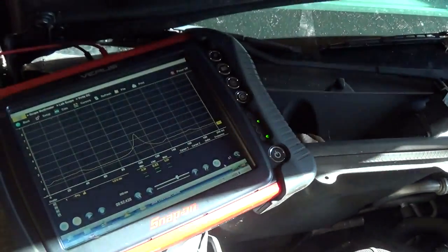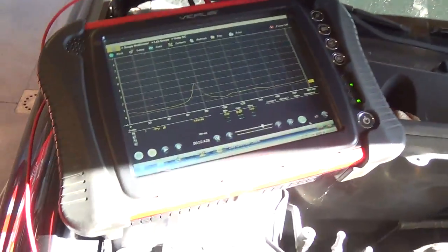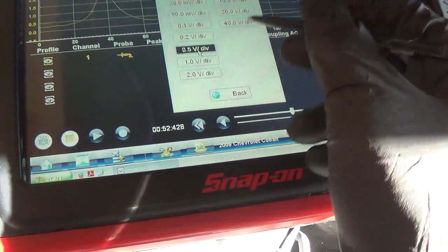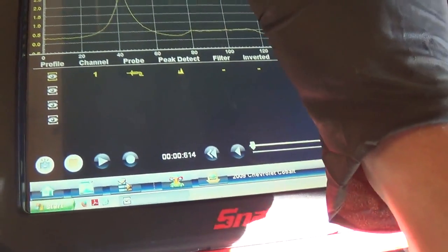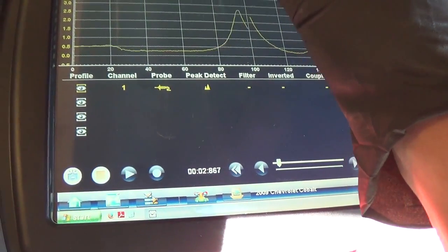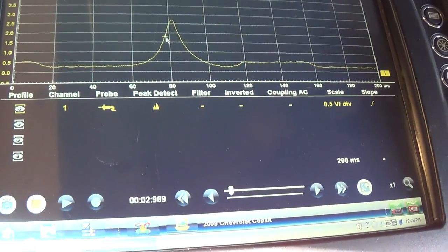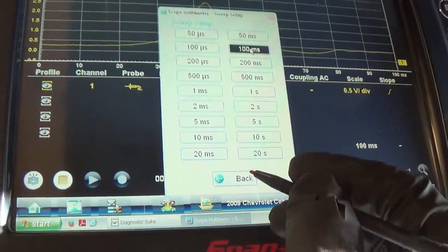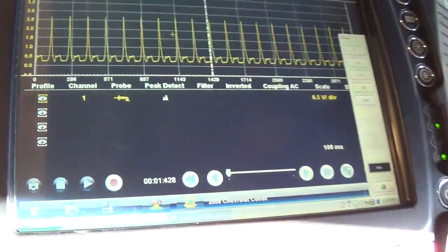Well, okay, we have a 2-cylinder misfire now, right? So let's drop this down. Since we're not looking at very high pressures, let's trigger on a rising edge. Right there. Okay, perfect. So 200 milliseconds, we can even go 100 milliseconds and stop it. Zoom out. Shut her down.